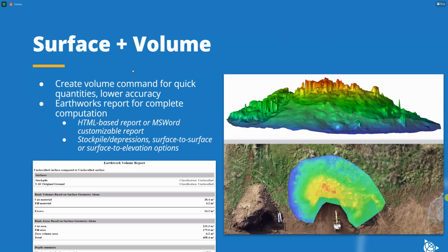Moving along to surfaces and volumes. So create volume commands for quick quantities, that is with lower accuracy. And then you have your earthworks report for the complete computation of the volume. So it gives you an HTML-based report, or Word customizable reports are available as well.